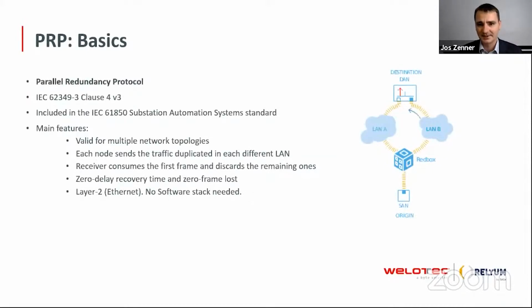Talking about PRP. PRP is a redundancy protocol in substations. It's a network-based protocol, so it works on standard TCP/IP. And it connects each device to two networks simultaneously.